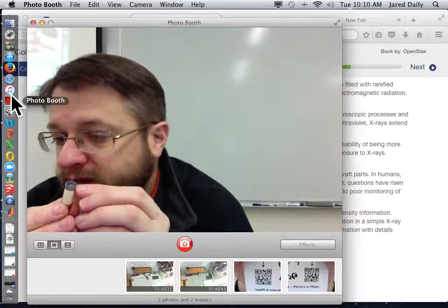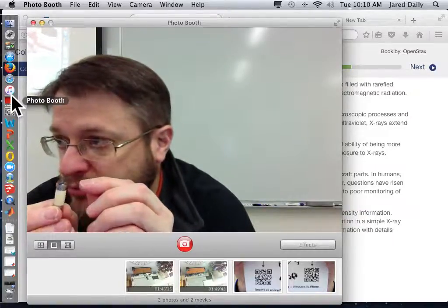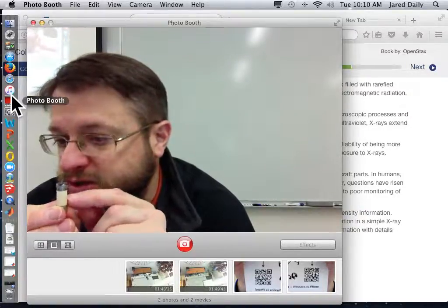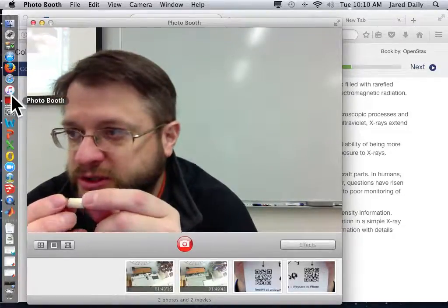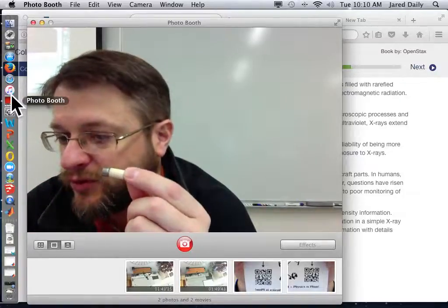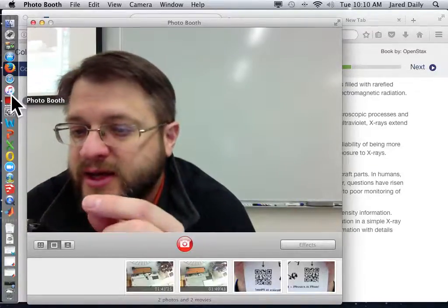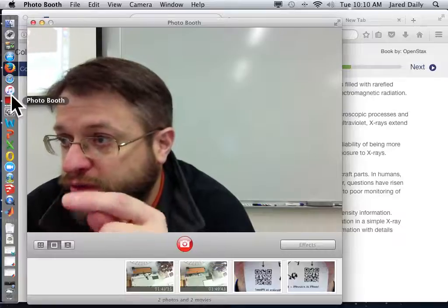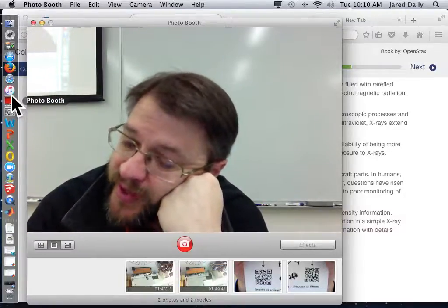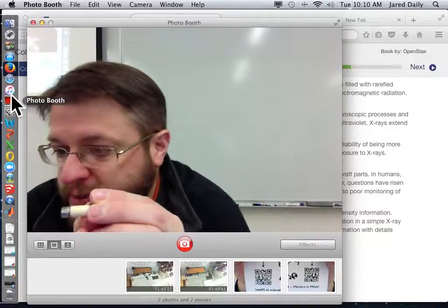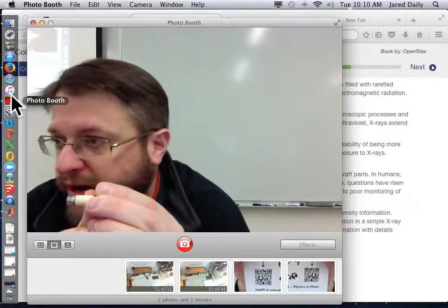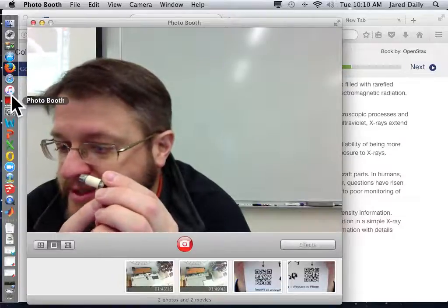This end is connected to a little light bulb inside of this tube here. This is a ceramic tube. And what we would do is we would put a huge voltage between the two ends of this, 40 kilovolts, 40,000 volts between the two ends. And then we would put a little current through the little light bulb and create electrons inside the tube. The tube in the middle is in vacuum, so there's no air or anything in between these two metal parts.